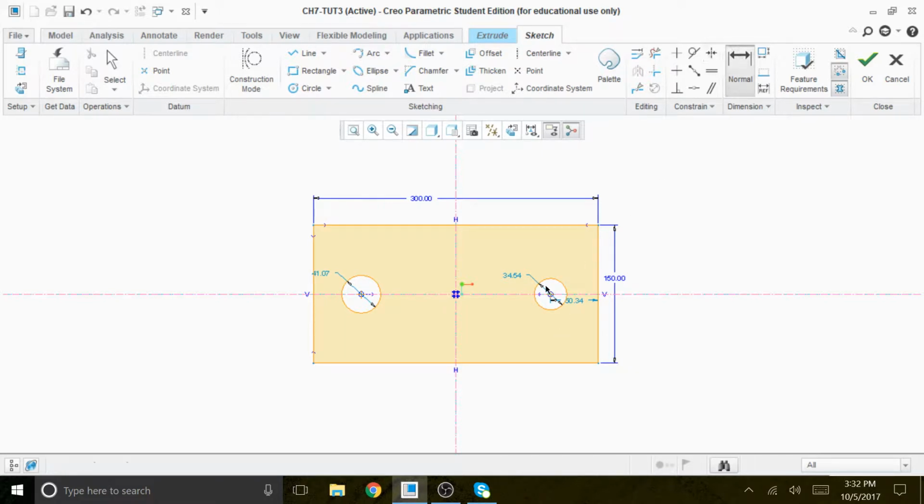So if I go from center to center, as 250, is it 230, right? 230. Okay, all right, 230. I'm always seeing those numbers a little bit off. So 230, and then the radius for the slot is 15. Okay, so let me just do this and say radius of 15.